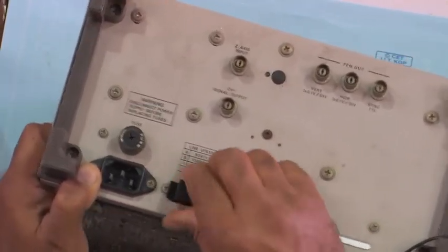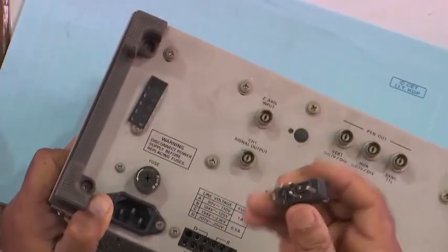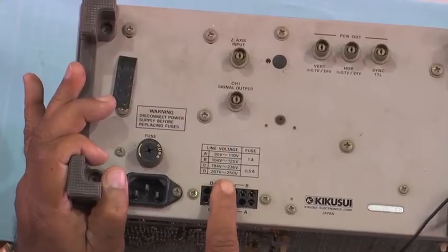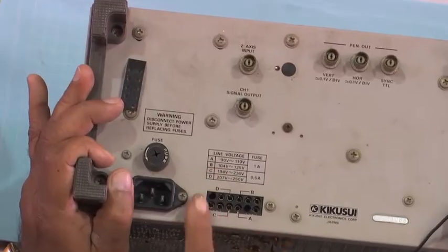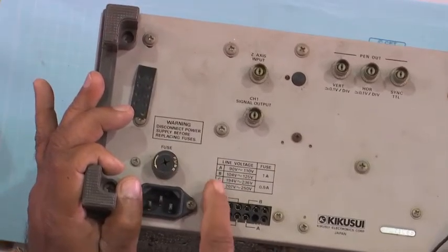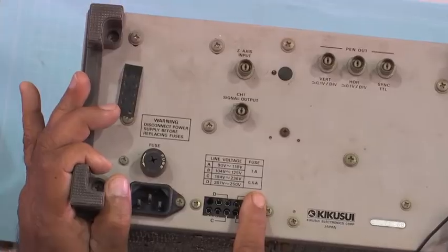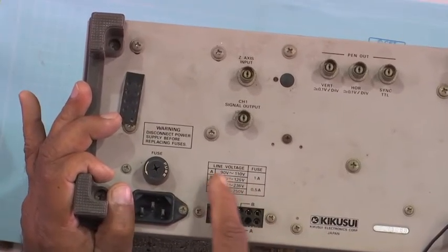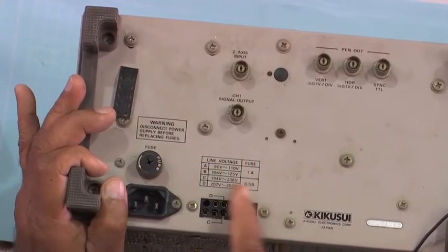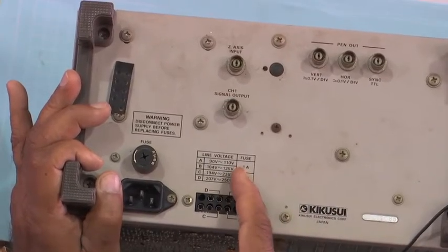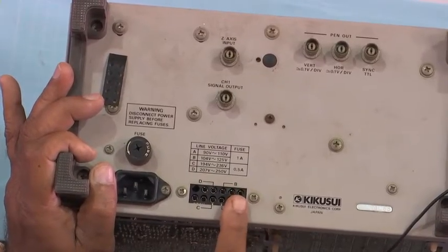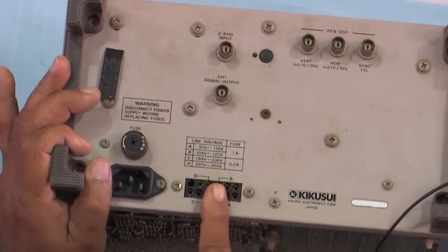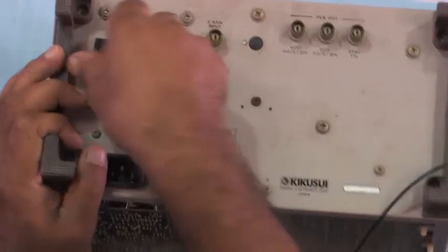This is basically the jacket, and here, if we have 220 volt, then you can use these two markings, AB and CD. For CD it is 220 volt, and for AB there is some range, 90 to 110 volt, 125 volt, and here 194 to 250 volt. In our country it is around 220 to 230 volt, so the CD range is suitable.